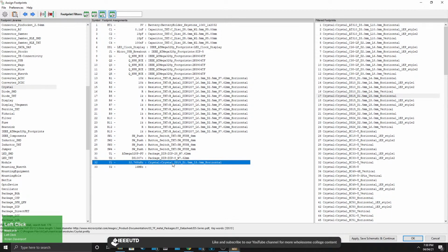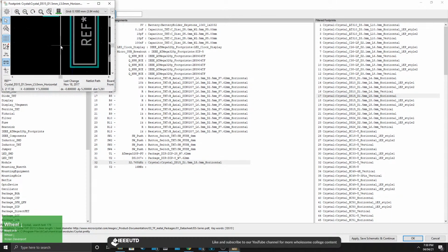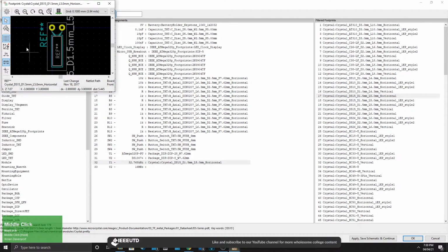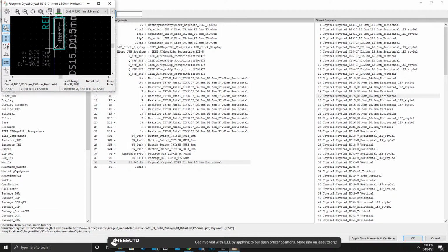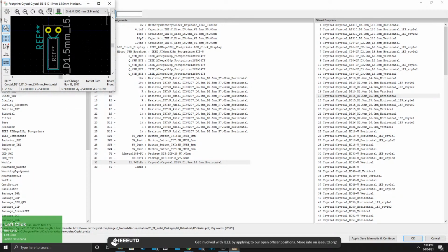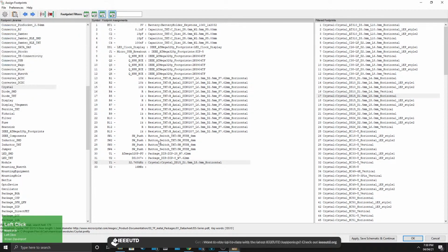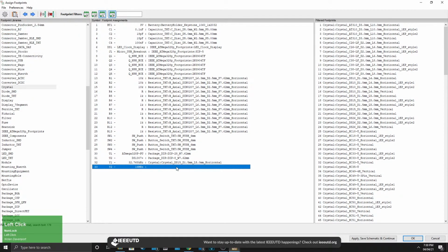1.5 horizontal. And you can see the resonator I had was approximately 5 millimeters tall. As you can see, this is about 6 something millimeters. Actually, no, this is actually 5 millimeters. So that works for me. That's why I chose that. It was one of those barrel resonators. So I chose that. And then we have our 16 megahertz crystal, which will actually be the clock for the